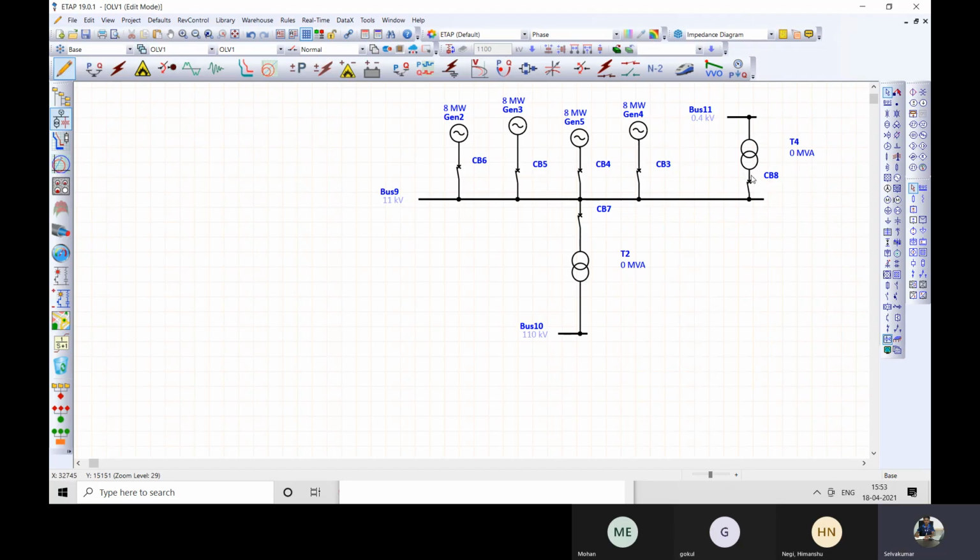When there is a fault immediately after the breaker on the transformer HV terminal, the fault current interruption will be extremely difficult for this circuit breaker, and the TRV will be much worse, because it has to interrupt the fault current not only from all 4 generators but also from the transformer. So the fault current interrupted by this circuit breaker is the highest among all the breakers, and its TRV requirements are much more stringent than all the other circuit breakers.